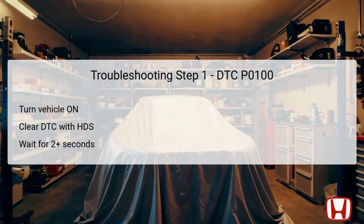Finally, after waiting, check for any pending or confirmed DTCs using the HDS. If DTC P0100 appears again, it confirms that the malfunction still exists, allowing you to proceed with further diagnosis. Proceeding to the second step involves determining the potential area of failure associated with the MAF sensor circuit.